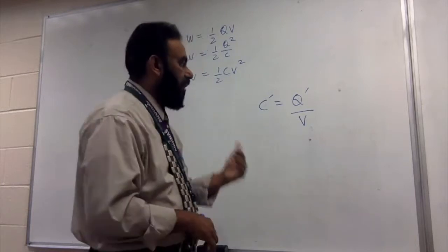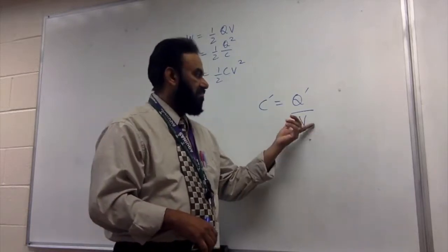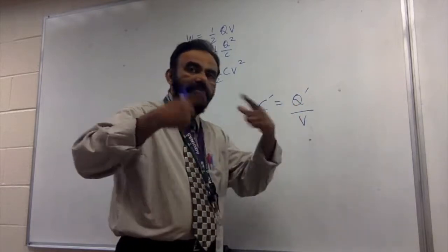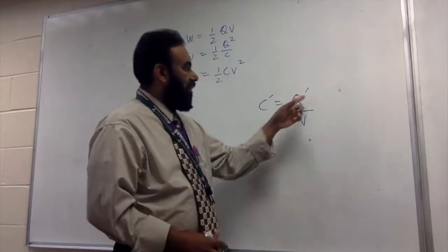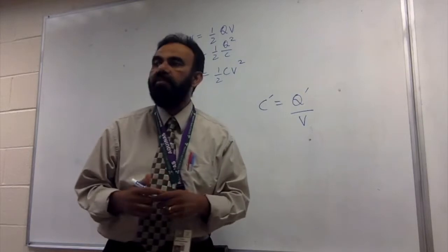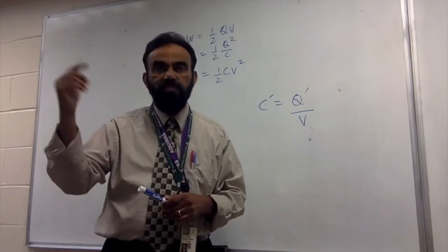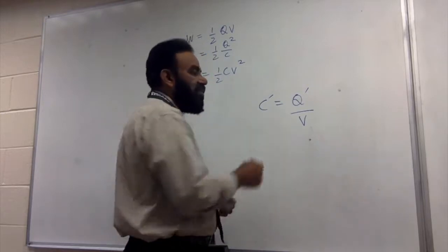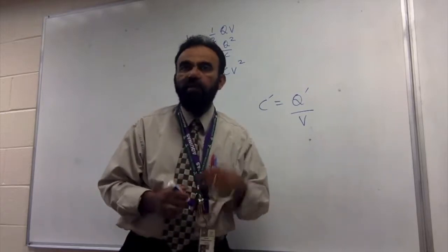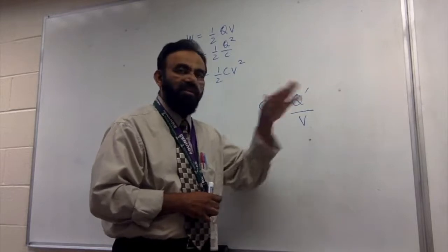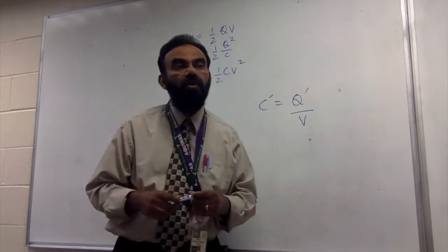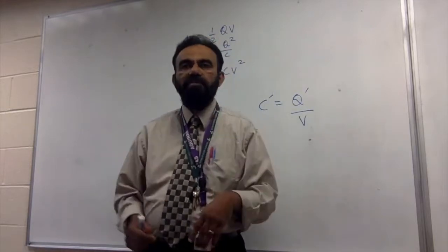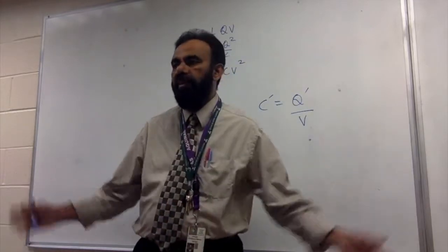So if you apply 12 volts to the capacitor, it is still going to get 12 volts, but the charge will increase. How many times does this charge increase? The same number of times as the permittivity K of the dielectric increases. So capacitance increases by K, charge increases by K. That's the online situation. Now the offline situation is where you charge the capacitor and then disconnect the battery.